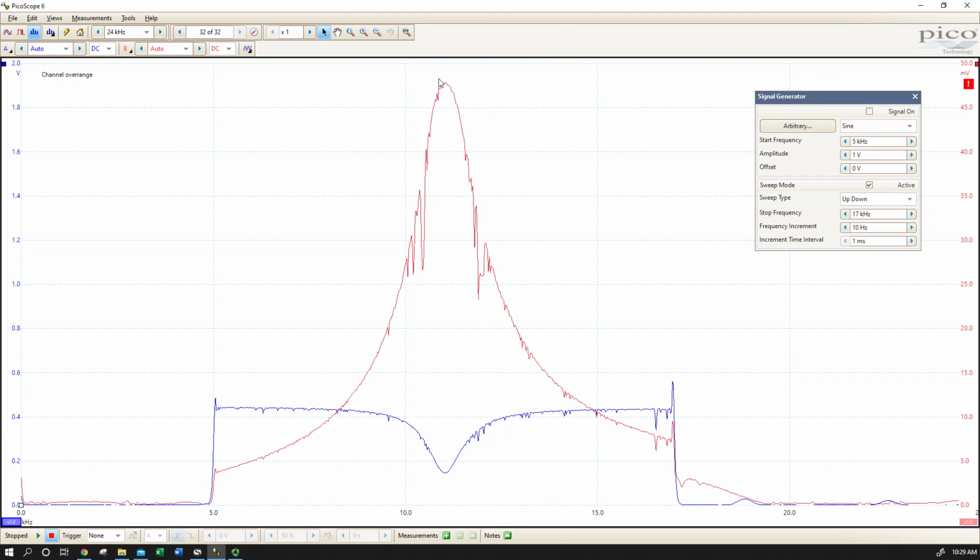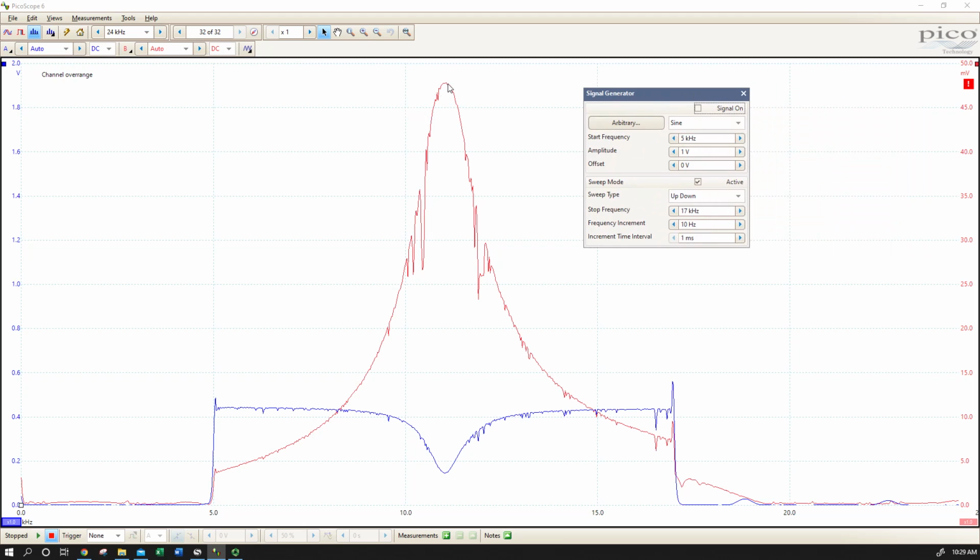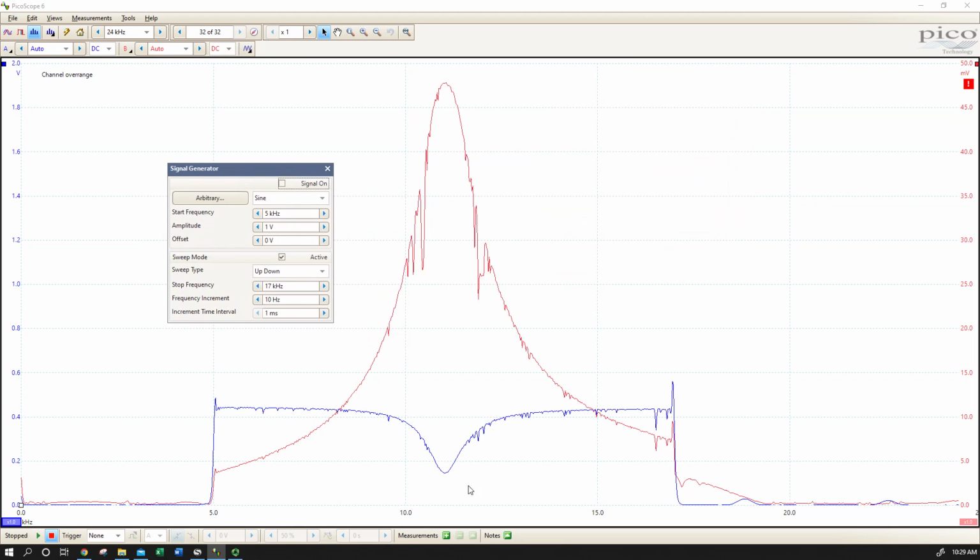We don't want to make any measurements on our resistor circuit, but we can take a look and notice that it is following the totally expected kind of shape. We're definitely seeing a high point in our voltage drop over that resistor when we have the low point over our whole circuit. So that's the expected resonance relationship. And in fact, we could even see how these values correspond to what we measured on our scope.